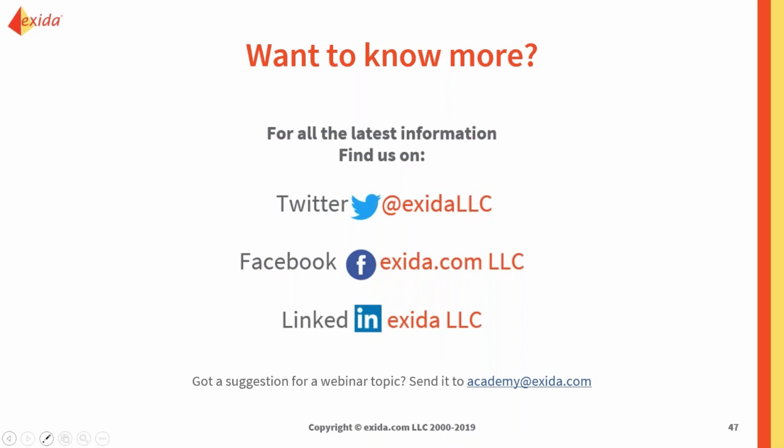Because so many people were trying to cheat the system and doing that 1 out of 1 for SIL 3, or we've even seen someone 1 out of 1 for SIL 4. And that's where that architectural constraint table comes in and says, no, this is a reality check. Just because you're doing the PFD average says you can, it doesn't mean you actually can. So ignoring that will violate that third barrier, or that architectural constraints barrier that you need to overcome.